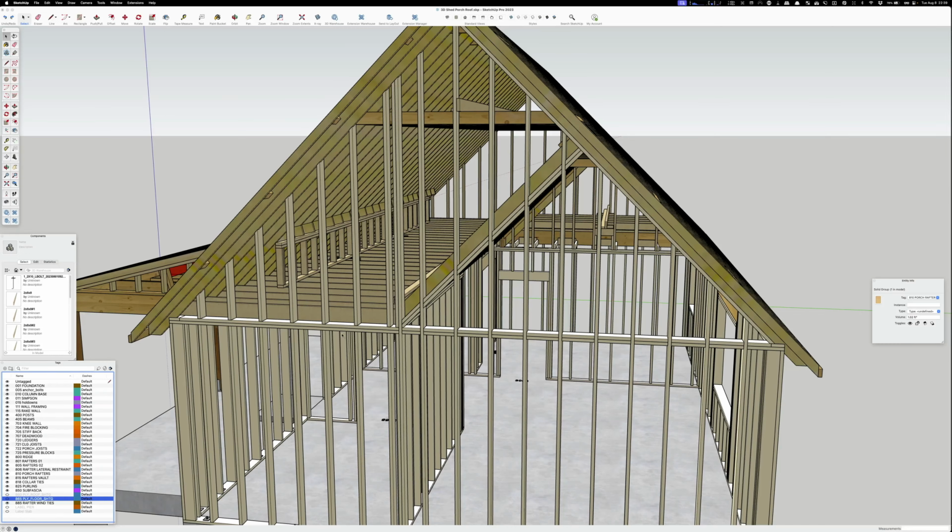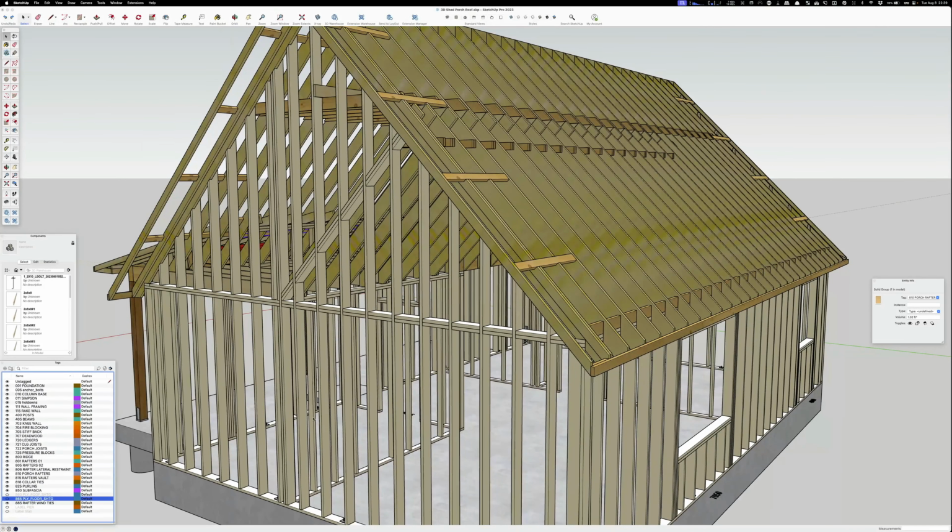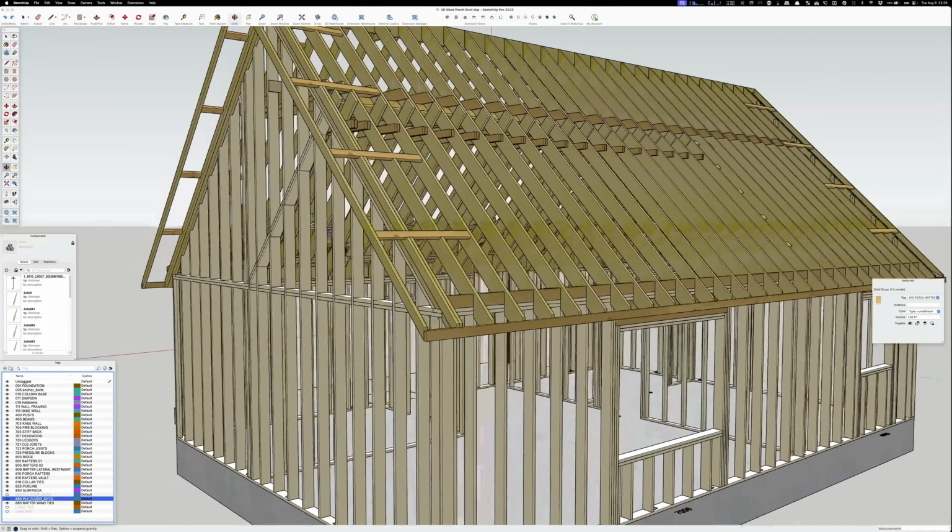And then these are blocks at plate height just to make it easy. If this is a 9-foot wall and they're running 54-inch sheetrock sideways, then they can go up and they'll hit wood when they go to attach it.